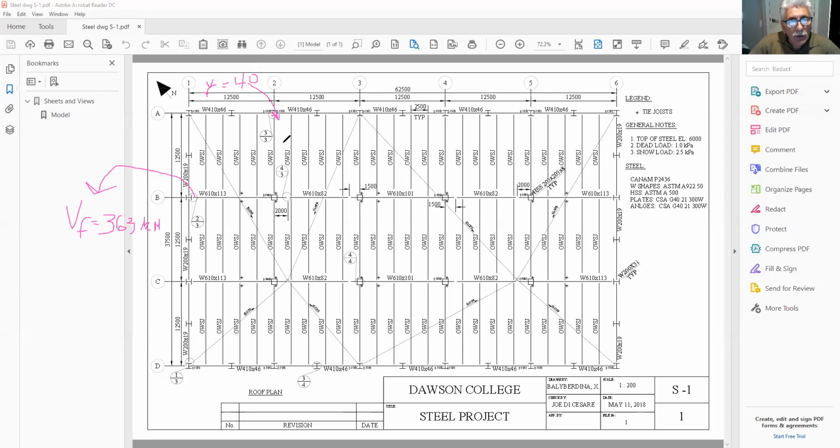Okay. Now keep in mind that when you're checking the thickness of the column here, you're going to be attaching it to the flange. So here you check the thickness according to the flange of this column. And I don't remember what we have specified, but we sized this column. This beam ended up being, not this one, we have a W 410. When we designed this beam, this ended up being a W 410 by 39.